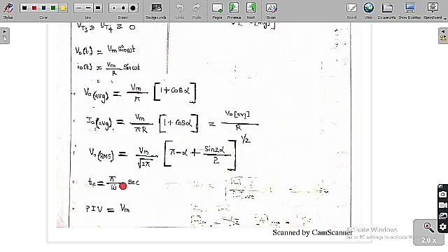And the circuit turn off time for each thyristor, because here for 0 to alpha, for T1 and T2, they are going to face a forward blocking voltage. From alpha to pi they are in the conduction mode, whereas from pi to 2 pi they are in the reverse blocking voltage. So only from pi to 2 pi they are going to face a negative voltage. Therefore Tc is equal to 2 pi minus pi, which is pi by omega seconds. So this is the circuit turn off time of T1, T2 and also T3 and T4.